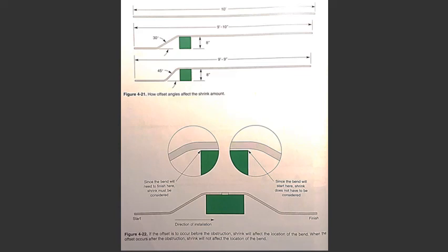Step 7 is to place the conduit bender handle on the floor and secure it in place with your foot. Step 8, place the conduit in the bender so that the first mark is aligned with the arrow. Step 9 is to bend the conduit to the angle determined in step 4, being careful not to kink it. Step 10, without removing the conduit from the bender, rotate the conduit 180 degrees and slide it until the second mark is aligned with the arrow.